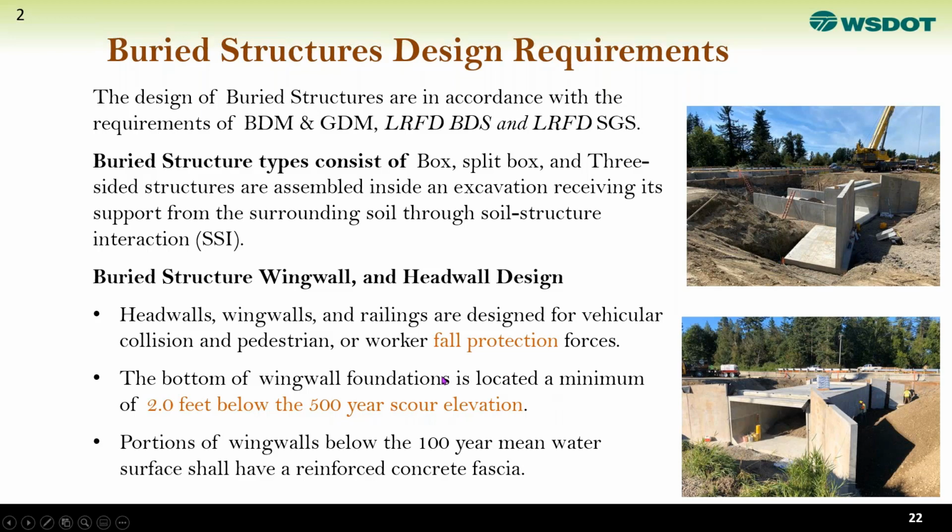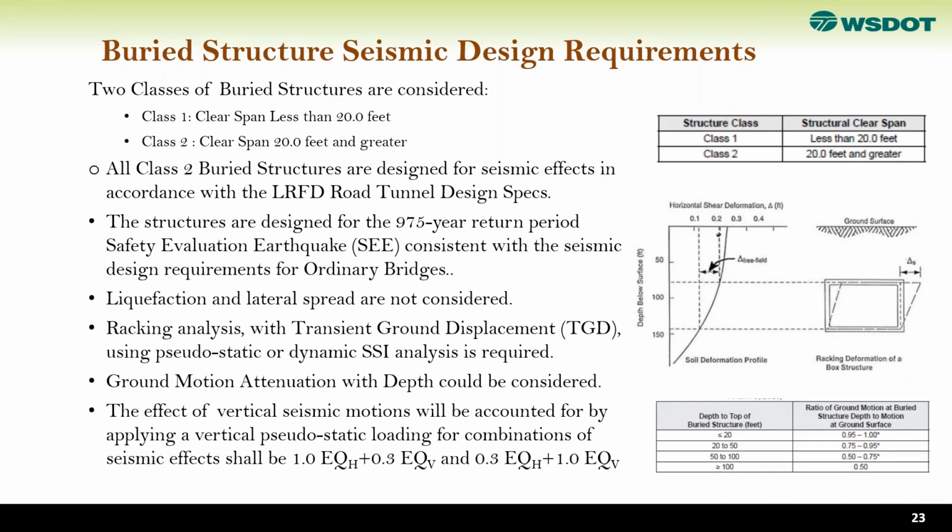So scour is a big deal in this fish passage program because this is all in Western Washington, on the stream bed where we are building this, and scour is a big consideration for that. Also, a portion of the wing wall below the 100-year mean water surface shall have a reinforced concrete fascia for long-term performance. So not getting much into the design, but just mention one in seismic, because this is specific to